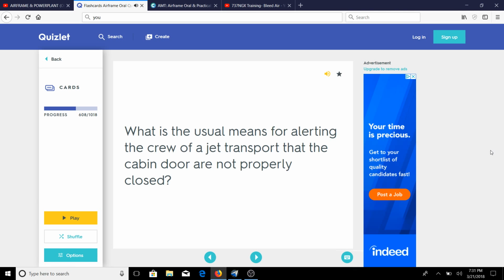The mass of the fuel. Who is authorized to apply the range markings to an instrument dial face? The manufacturer or a certificated instrument repair station.